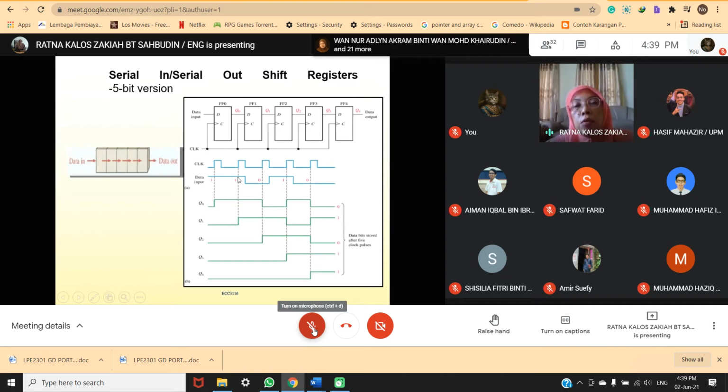And here at this clock, Q0 is high, so you have high. Until this clock here, this is still high, so it's high. At this clock here, this is low, so you have low. And this clock here is high, so you have high. And then this Q1 becomes the input for flip-flop number 2.